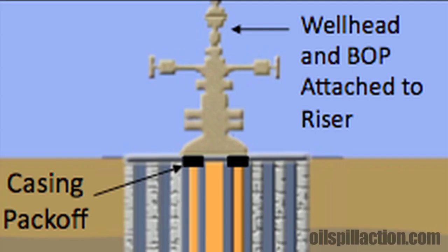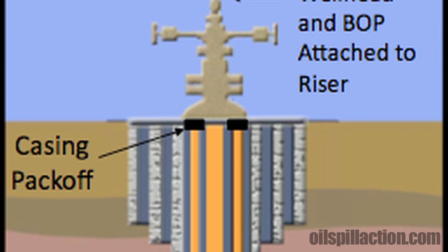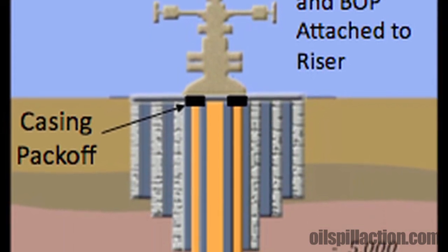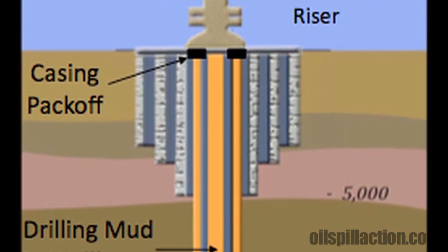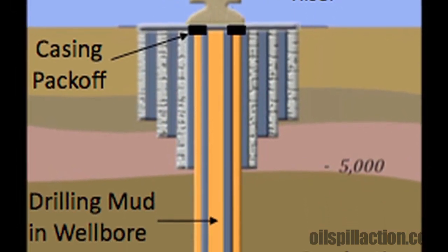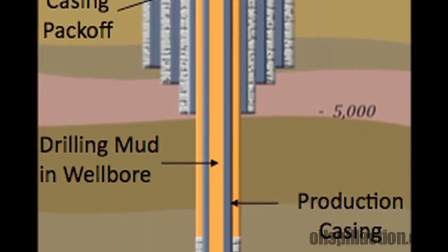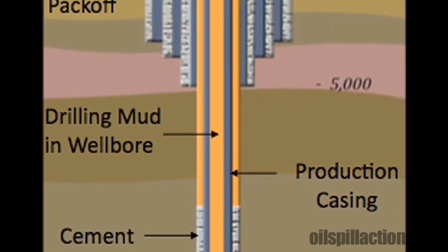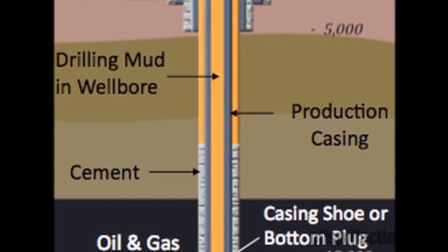Once that is accomplished, it's necessary to finish the well and move the rig off-site. After the requisite pressure tests are done confirming the integrity of the casing job, a cement balance plug should be set inside the casing to prevent against a blowout. Once the balance plug is set and pressure tested, then the mud in the riser, the mud that is the primary means of well control that's in the pipe from the rig down to the blowout preventer, is removed, and seawater is placed in there, and then they can remove the riser and the rig can move off site.